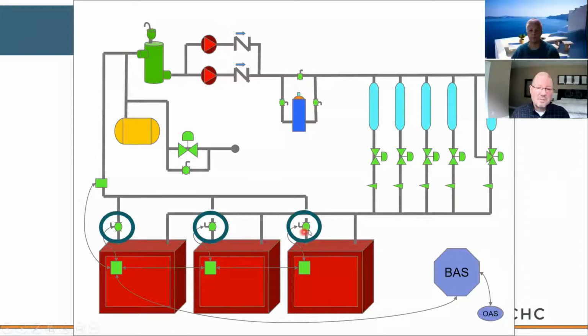So these motorized isolation valves, those are also very important. Now, we have a lot of engineers that say this is the cheapest way to do it because these are going to cost less than a dedicated boiler pump. Not really. These valves are about the same cost as a boiler pump, so it's kind of a wash. Your other challenge here is if you're in a retrofit, this can create some challenges because we have added some pressure drop to our system pumps. So you have to be careful with how you apply this. New construction, no problem. Okay, but existing, be careful.